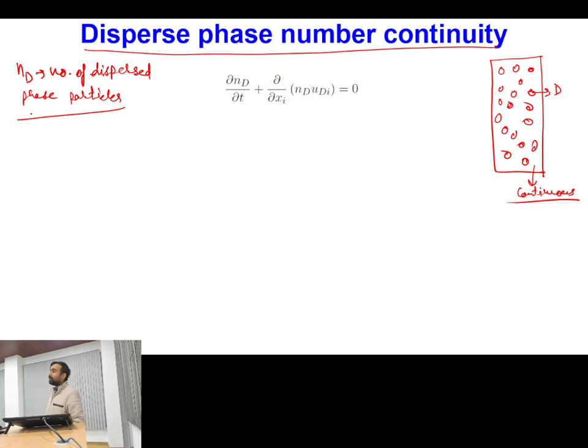Okay. So what will the population balance method be doing? It will first keep track of the number and volume of bubbles present, and then using some mathematical models, it will lead to breakup and formation of a single bubble into multiple, or coalescence of a number of bubbles into a single bubble.